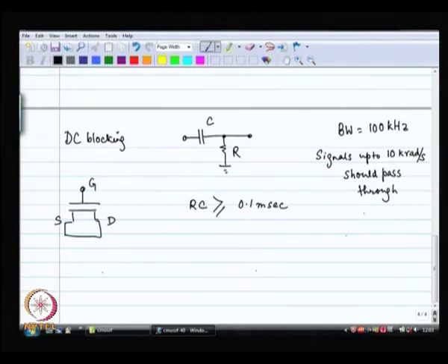This is the way we studied the MOSFET in fact, right. So, you have got a thin oxide layer in between, and that separates the gate and the channel, and that is your capacitance Cox. I mean the density Cox density times the width times the length. So, typical Cox densities could be something like 8 femtofarad per square micron.